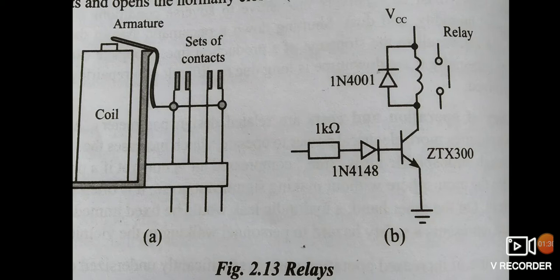For the relay shown in the figure, when there is a current through the solenoid of the relay, a magnetic field is produced which attracts the iron armature, moves the push rod, and so closes the normally open switch and opens the normally closed switch contacts. Relays are often used in control systems.